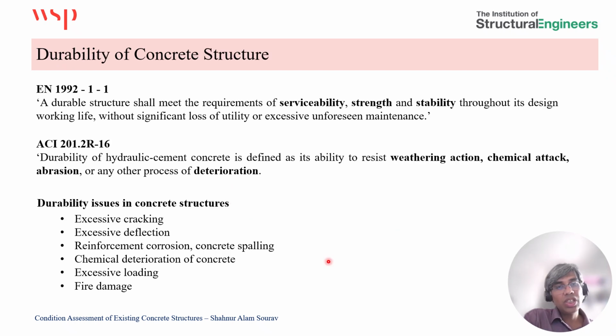So here's the definition of durable concrete structures. According to EN 1992, a durable structure shall meet the requirement of serviceability, strength, and stability during its design life. But there is another thing here which is important: without significant loss of utility or excessive unforeseen maintenance.